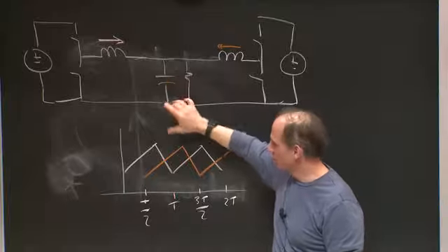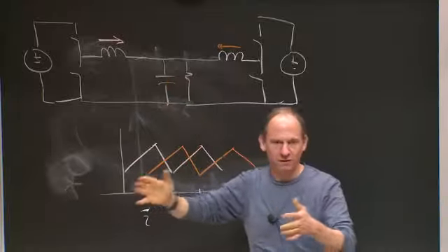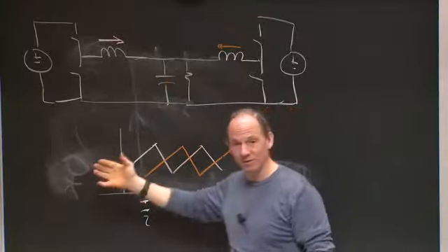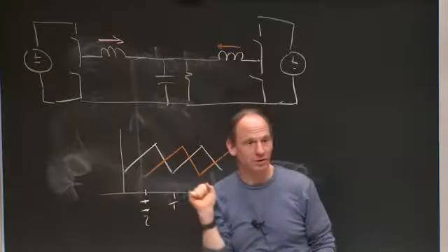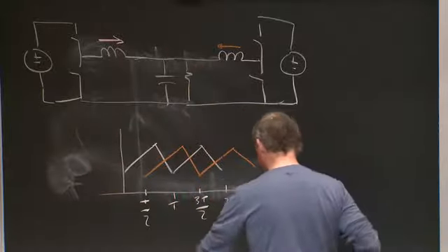All right? So this same kind of trick of harmonic cancellation, here I'm canceling the fundamentals because what I would like is a DC output current. This technique is called interleaving.